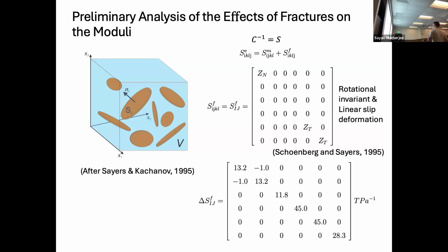As you see, the 6 components along the diagonal all have some numbers associated with them, and that means not a single fracture size is capable of describing its contribution to the elasticity. For the off-diagonal components, they are either 0 or very small, which means these fractures may exist in orthogonal sets, which agrees with the overall image log.